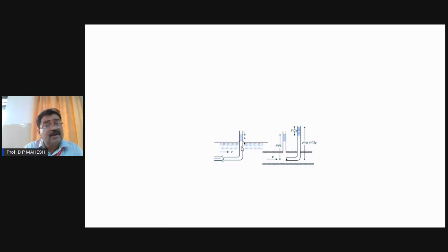but it is used to calculate the velocity. Directly, the pitot tube is used to calculate the velocity, and we use Bernoulli's equation for this point and this point, using which we can calculate the velocity, and that formula is root of 2gh.